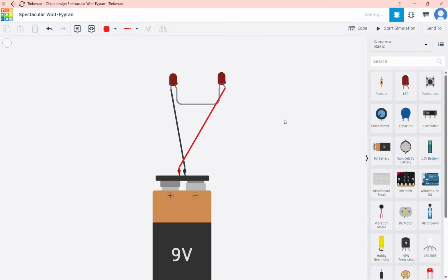Now every LED has a maximum or drop-down voltage. For red, they have the least among all LEDs, which is 1.2 volts, and I think the highest would be violet followed by blue. So since this is 9 volts and this 1.2 is connected to this 1.2, since this is series connection, we get roughly 2.4, which is far lower than 9V. So we are going to change the color to blue so that we don't blow our LED up.